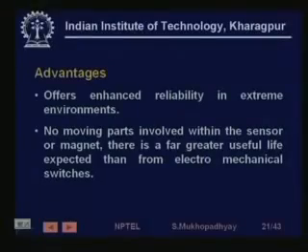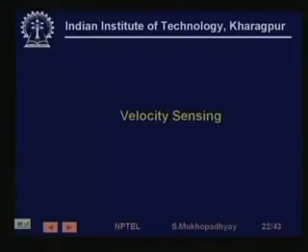It's also very small. The only thing is that the level of signals which comes from the sensor is low, so you need to amplify the signal. Often you get Hall effect sensors with some integrated electronics to amplify.